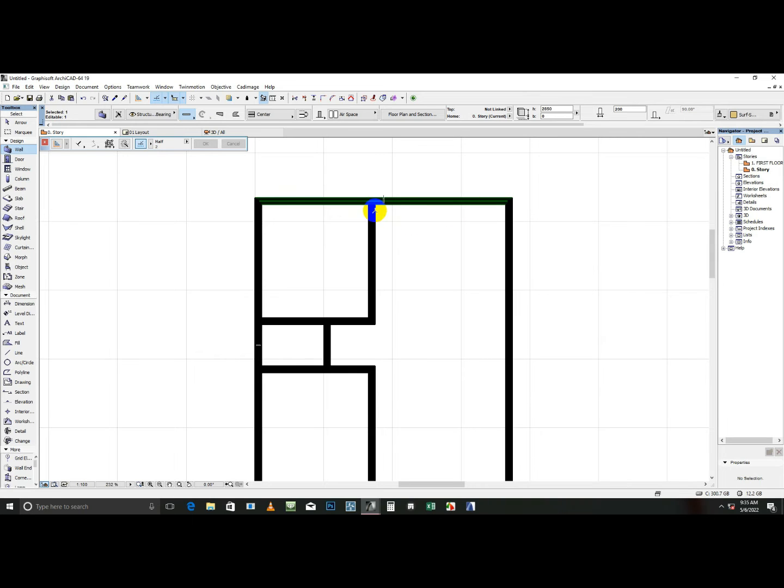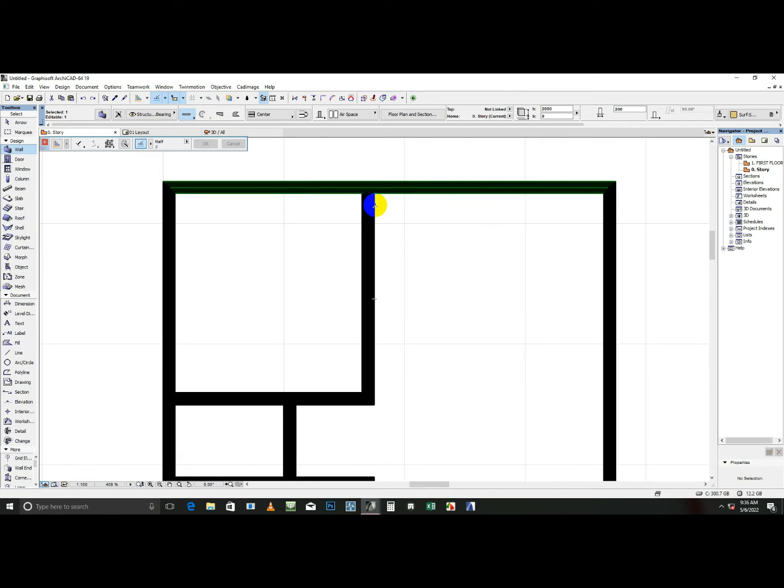I want to split this wall into two. One wall to get up to this position, the other one too. So I highlight that wall, come here, say split, select that split button there. I can split like that, or rather I can highlight, then press Control and place my cursor where I want the wall cut.